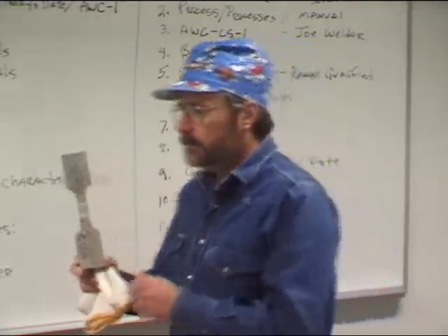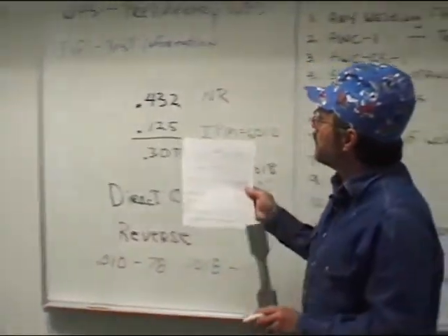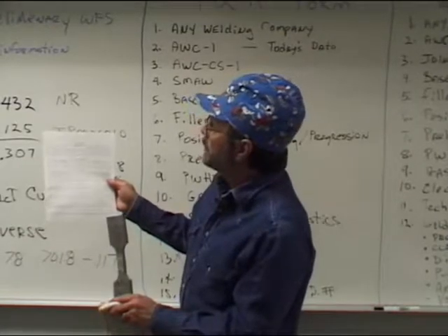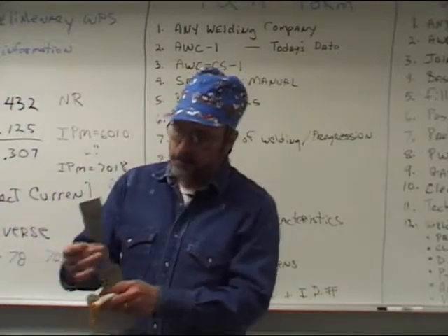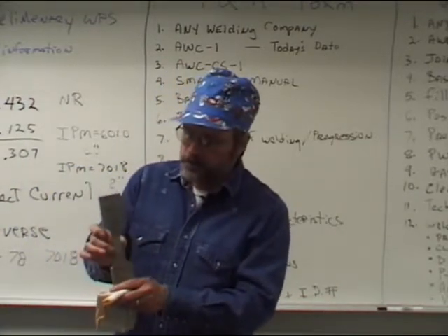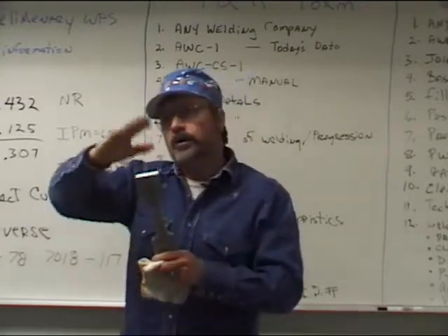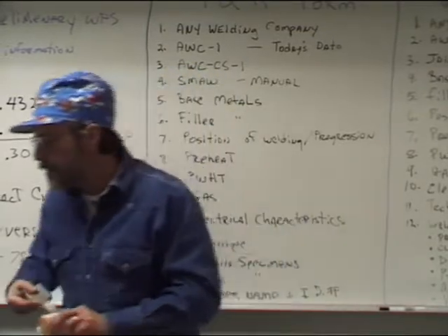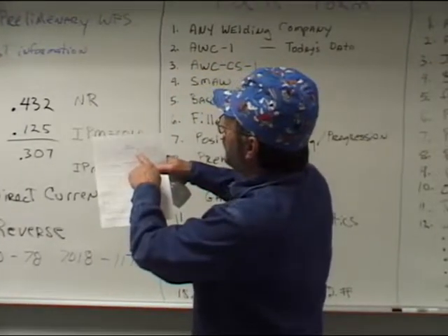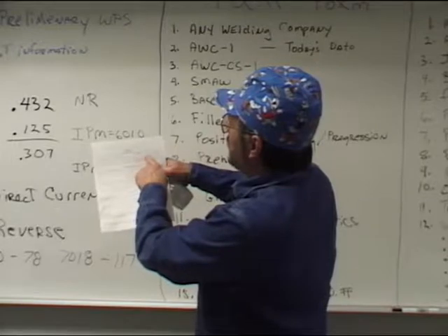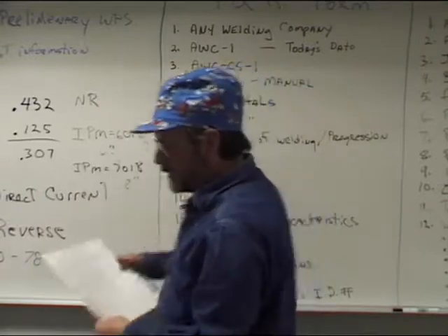And you'll notice on that form, on the back side, where it says tensile, it says specimen number 1, and then width and thickness. Then you're going to calculate the area. So we're going to measure this, and you notice it's machined down so that we get it nice and smooth all the way down through there. So we're going to measure it, calculate what that area is, then we're going to put it in our tensile puller, and we're going to pull it apart, and we're going to note how much force it took to tear that apart, and then from that, we can calculate the ultimate total load, and that will be recorded right here. And then from that, you'll get the ultimate unit stress, and then you need to record the type of failure and where the failure occurred at.